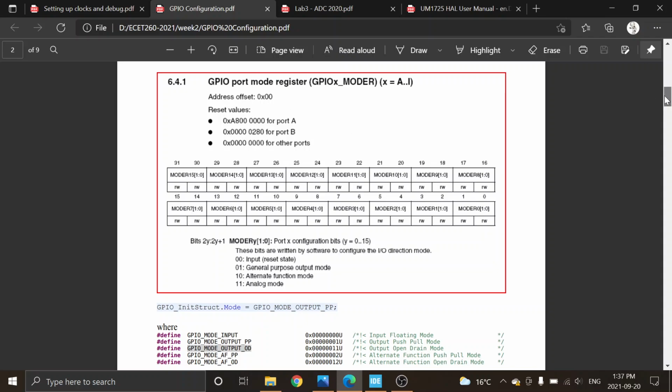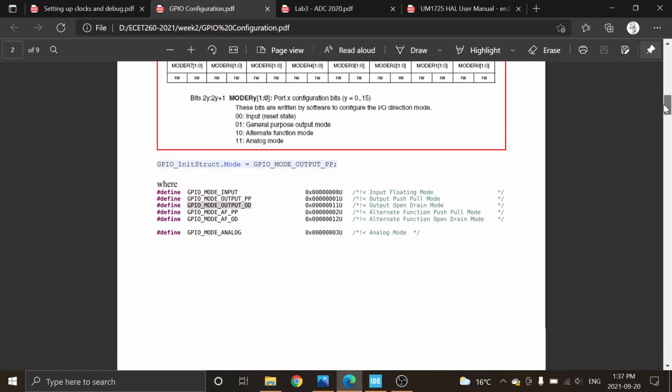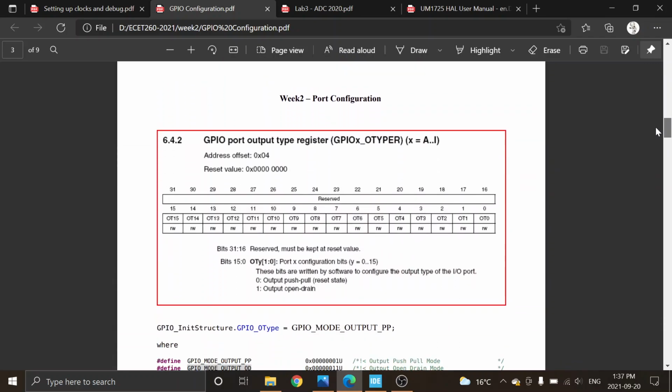And then we go to the next register, and that's a 32-bit register, so there's 4 bytes. And the next is type. In this case, it says offset is 4, because we're already 4 bytes up from the previous 32-bit register. And in this case, we have a 32-bit register, but the top is reserved, and they only use the bottom bits for it. So it says here, bits 0 to 15.